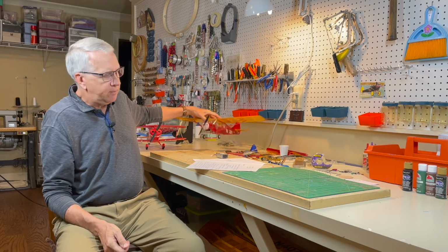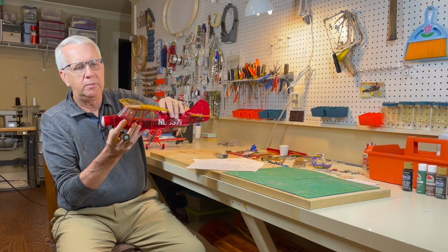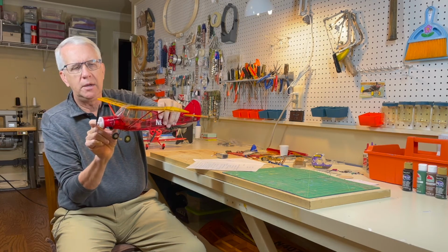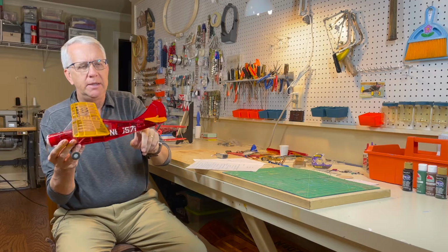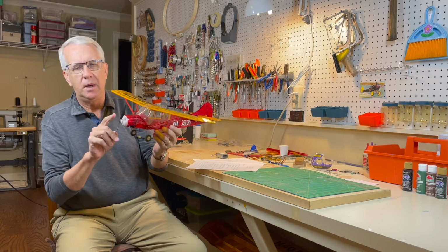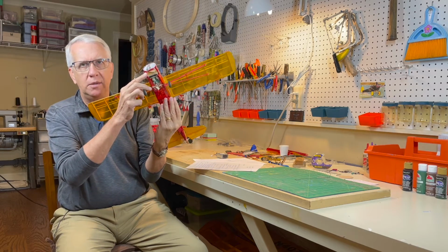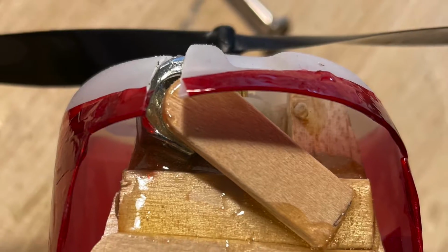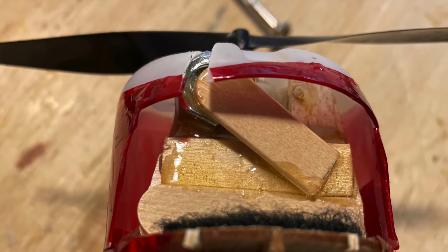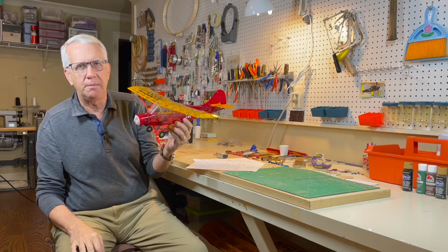The bottom line, though, is the plane has to balance at the center of gravity. You have to do whatever is necessary to balance that airplane on the ground before you fly. It could be adding weight to the nose, adding weight to the tail, but you have to balance out the aircraft. A good example of this is the Aeronca. It's a little bit short nose moment. These planes always tend to come on a little bit tail heavy with the structure in the tail. Weight is super important on these Guillow's models, but I'll show you that I had to install some weight. A couple iron bolts had to be glued into the nose to allow this airplane to properly balance.